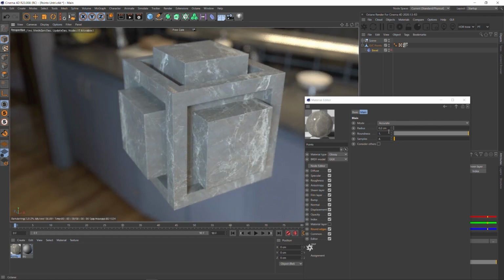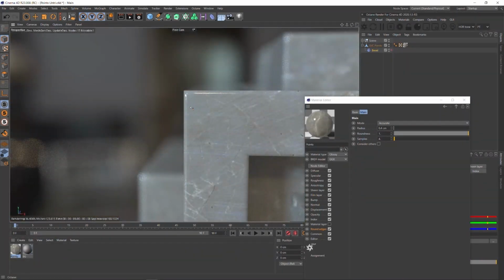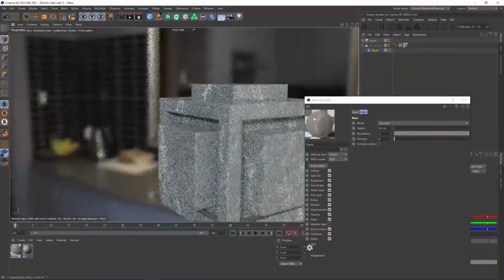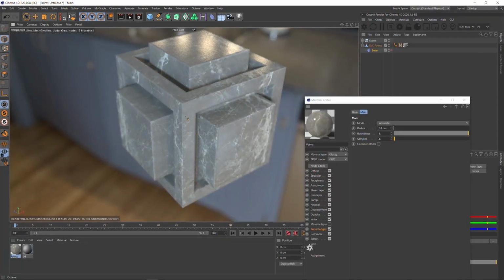And now you start to see that rounded edge show up. And we're faking it essentially, because if I scoot in on this, you can see that these edges are still pinpoint sharp, but I know I'm not going to be that close on it. So I've just saved time in untriangulating, in massive optimizations, mesh checking, and cleaning the mesh up so that I can make way for this bevel tool and just use the rounded edge shader. This is a huge, huge, huge benefit to dealing with CAD models. Very important to have in your toolkit. So understand how your renderer deals with it and make sure that you're using it.